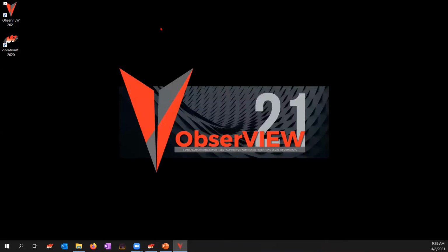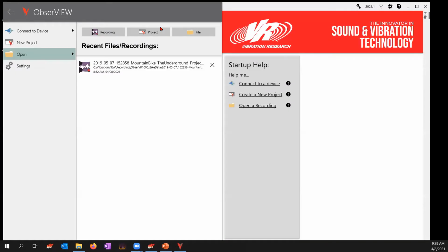So the ObserView software here is a free-to-download time history analysis software. What you can do is take your time history files captured from any data acquisition system and copy, paste, put multiple files together, taper the data so that it's ready to be played on a shaker, right? You can also do FFT analysis in the free version. So there's a lot of capability here.